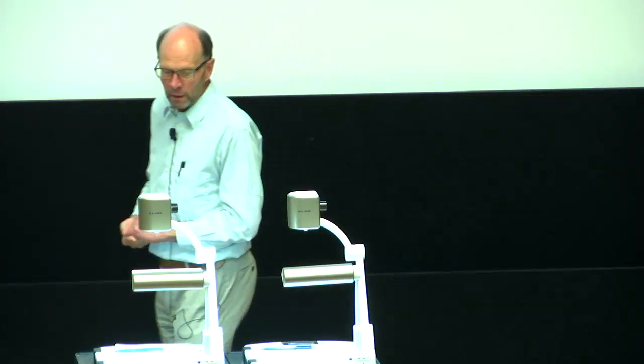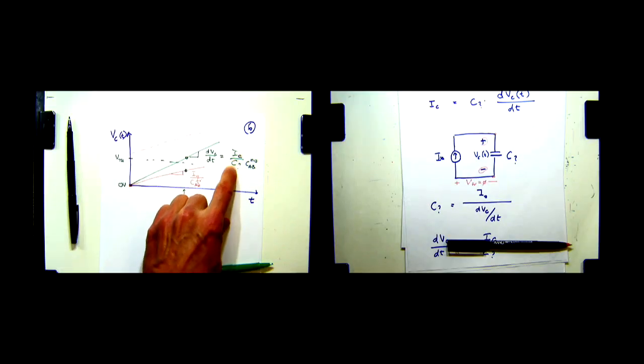Now the value of the capacitor could be different because the person may have lifted the finger or left it there. So to answer your question, yes, under those circumstances, if neither I0 nor the capacitor changes, then the slope is constant, and yes, it's a straight line. Make sense?